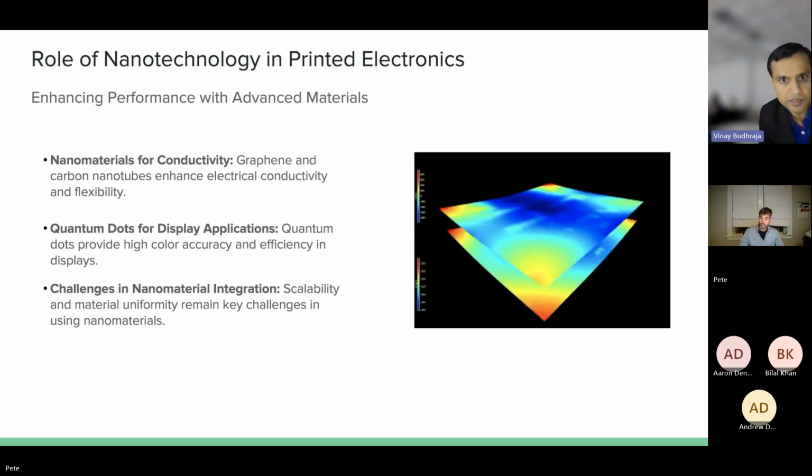How is the stability of the graphene ink? It depends on the ink. A lot of people, what we're finding, are formulating their own. There are some commercially available graphene inks out there, but a lot of people want to develop their own based upon the electrical capabilities that you're trying to accomplish. Quite stable. You really want to stay away from solvents that are highly volatile, so something like toluene or lower in volatility.